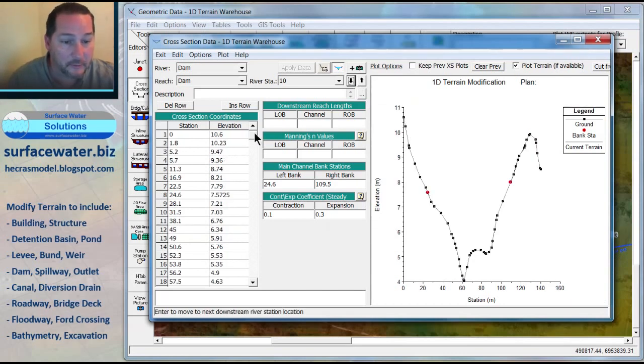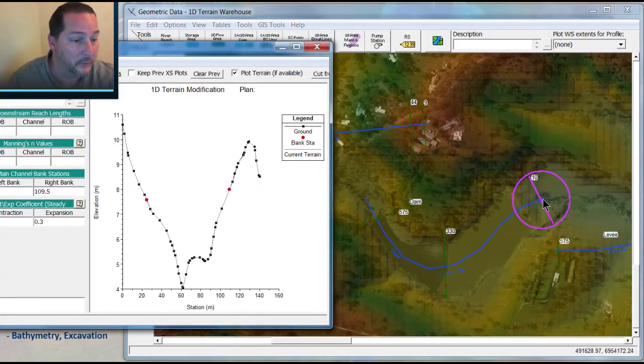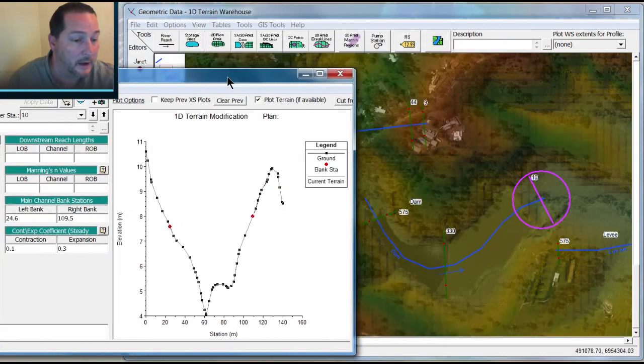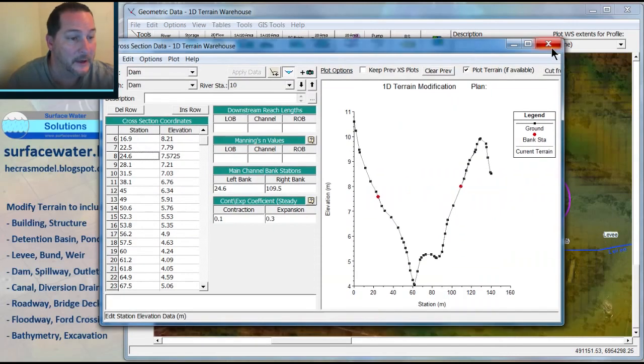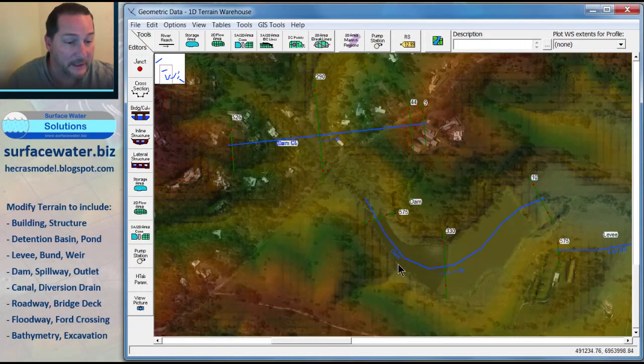And on my last one, let's try doing it with just a single section in here, a single point in the middle. Actually, no, this one is going to be the end section right here, which we're going to use to interpolate out to this one. And just have a look at what this looks like in the end when we interpolate out here. You'll see that it's going to gradually transition from one section to the next using that center line alignment. Again, you can add as many points as you'd like. You could take real bathymetric section data and put that in there. Now, 2 more to go.